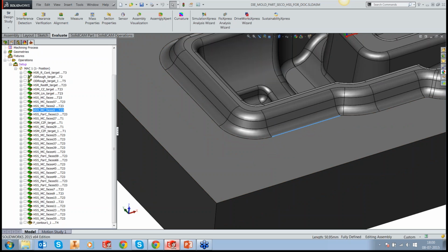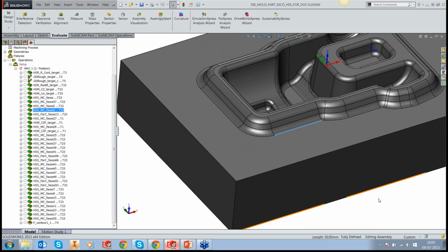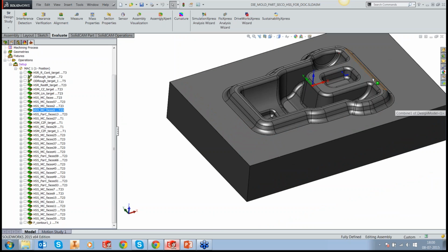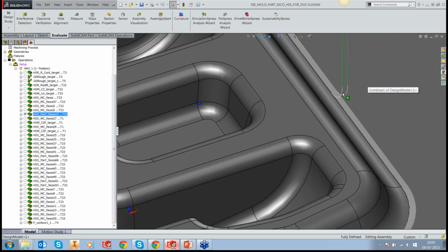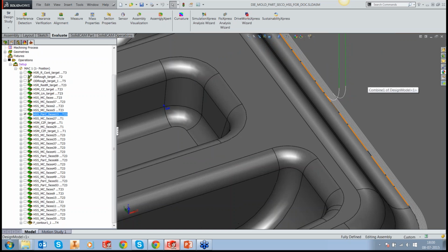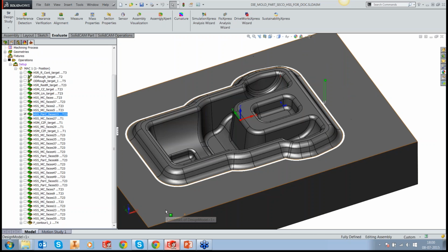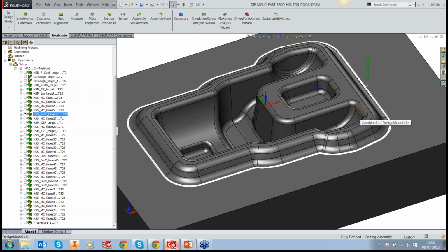It could be like 25, 30 microns of material remaining on that line. So in order to sort that out, we used another few passes parallel to curve and overlapped into our flat area. Okay, so that takes care of the fillets, this fillet, surface, the fillet, and the overlap.